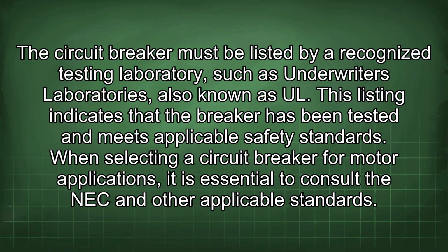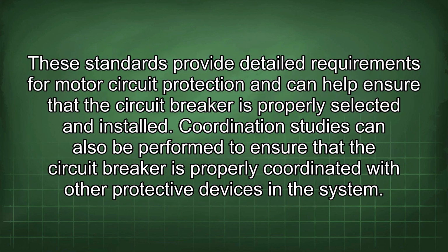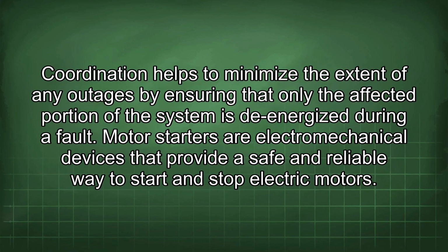When selecting a circuit breaker for motor applications, it is essential to consult the NEC and other applicable standards. These standards provide detailed requirements for motor circuit protection and can help ensure that the circuit breaker is properly selected and installed. Coordination studies can also be performed to ensure that the circuit breaker is properly coordinated with other protective devices in the system. Coordination helps to minimize the extent of any outages by ensuring that only the affected portion of the system is de-energized during a fault.